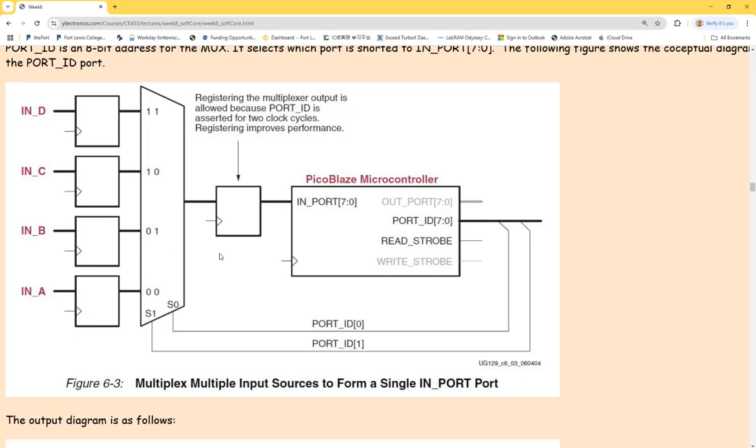So it doesn't have the physical pins of the chip, right? You don't have that many pins for the package, but for internal pins, you can add as many as you want. By looking at this example, you can feel some of the advantage of using FPGA over microcontrollers. Microcontrollers are basically just C program instructions, right? So it has to be the instruction pointer taking them out one by one each time, and you have no freedom or options to modify the hardware. So it has a lot of limits.